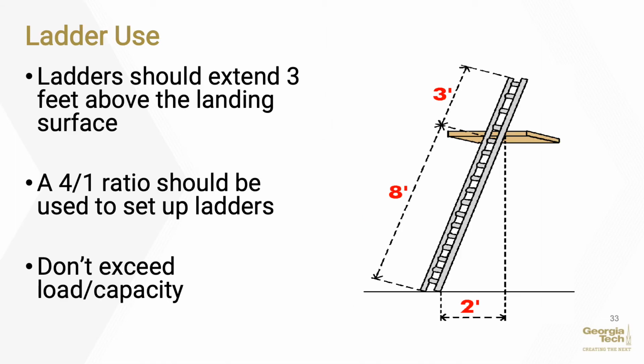Ladders should extend 3 feet above the landing surface. A 4-to-1 ratio should be used to set up ladders. Do not exceed the maximum intended load of a ladder or the manufacturer's rated capacity.